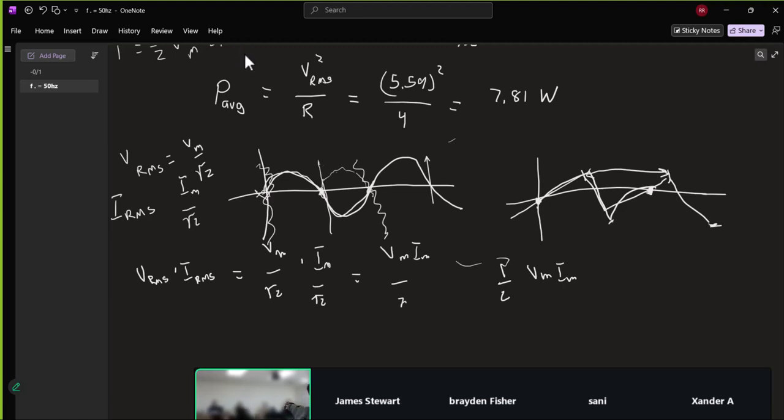Oh, I wanted to ask how the VRMS, IRMS relates to a DC baseline for any sort of voltage or current. So the VRMS, IRMS equals the average power. And so that would correspond to the power that you would get from an equivalent DC circuit. Effective. Effective, yes. So a DC circuit that had a voltage of this VRMS. I didn't get the effective DC equivalent.